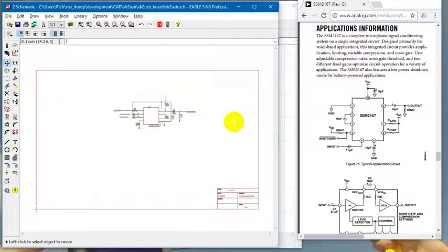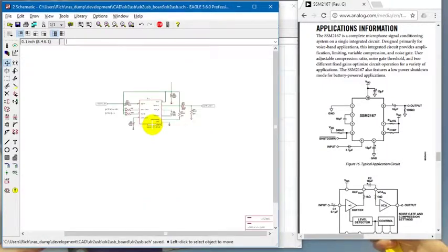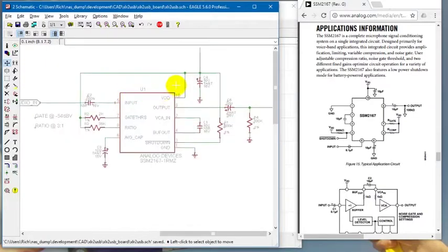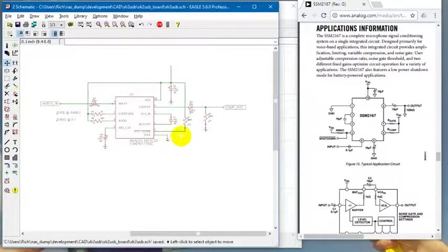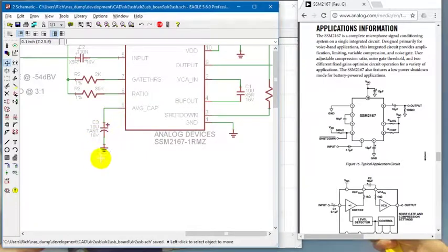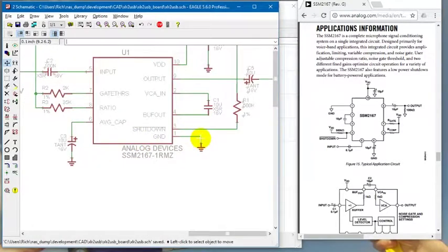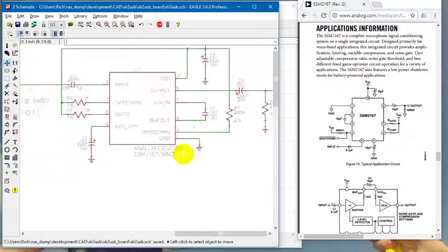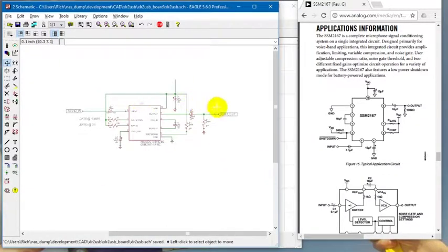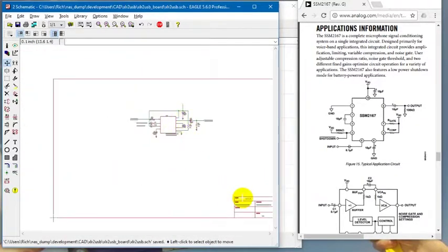Okay. So our schematic is coming along pretty well. We've gotten through a few basic things. How to add a part, how to change a library and get an update from a library, how to smash parts, pull them from libraries, what the concept of supply nets and supply pins are, and why they can change things and make your life easier, because obviously everything with that symbol should be a ground, right? And so on, and flyouts and attributes and things.